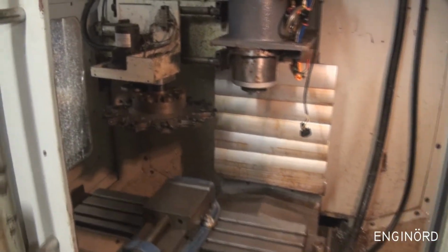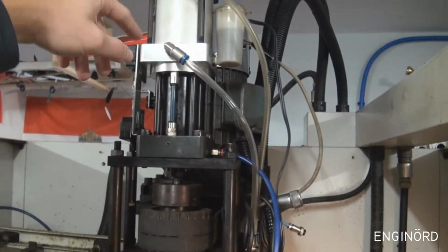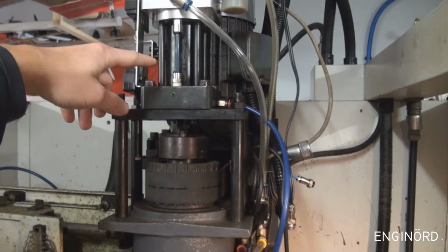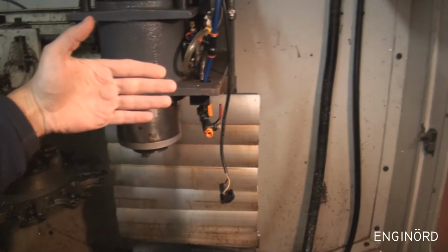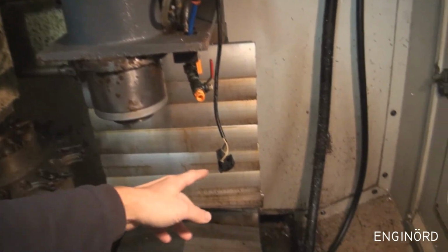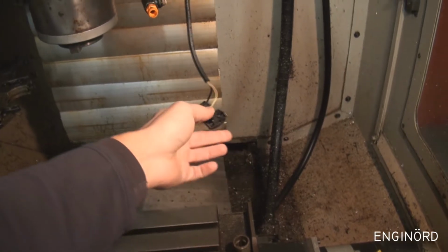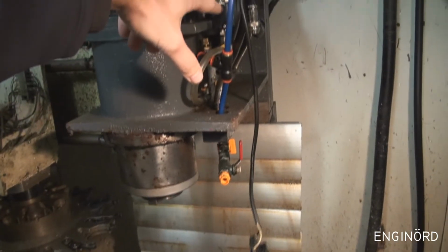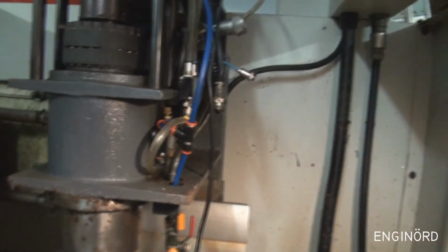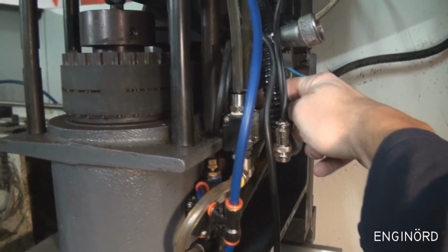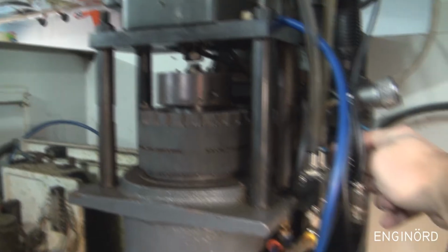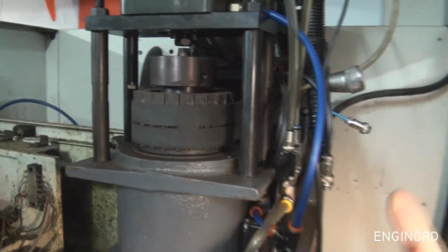But I'm particularly curious about, first of all, the cylinder here. So this is a pneumatic cylinder that actuates a hydraulic cylinder. You can see there is end stop, so there's 2 switches here, and typically this is being covered by a panel, but I removed it, and this is the switch that operates it. Now when I press the switch, see, nothing happens. What should actually happen is this valve here should operate, and I can go and there's an override switch here, and I can manually operate it, and you can see that the cylinder works. If I manually operate it, the cylinder works.